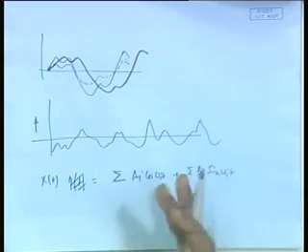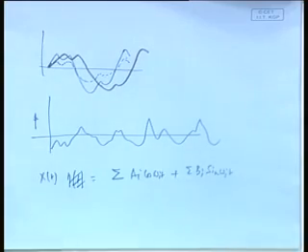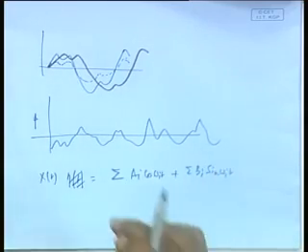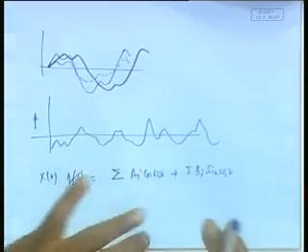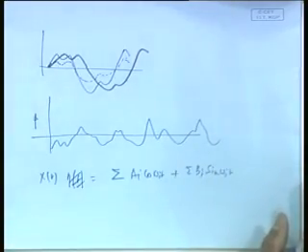We will see that this becomes the starting point, as we will see next class, for representing a random wave or random signal as a wave spectrum, in which the amplitude, meaning height, and the frequency, meaning period, will be connected to each other. This we will see in the next class when we actually go for the spectrum. But what we learned today is an important and interesting observation that wave-height distribution is not normal but Rayleigh. Therefore, I should use H 1/3 more, and then it being Rayleigh, everything is connected to each other. So up to that we have learned in today's class.